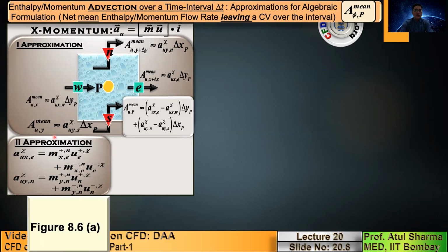So this introduces a nonlinearity. Depending on whether you are using explicit, implicit, or Crank-Nicolson, this u velocity is taken accordingly; if you are using an implicit method, it could be implicit. But note that to avoid the nonlinearity, the technique that is used is that the mass fluxes are always taken explicit in the advection term. Okay, so this corresponds to the x momentum flux.